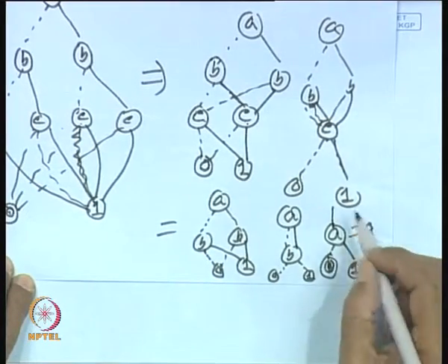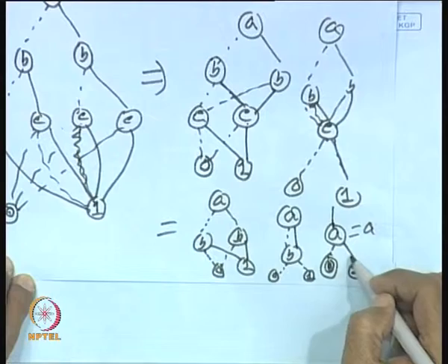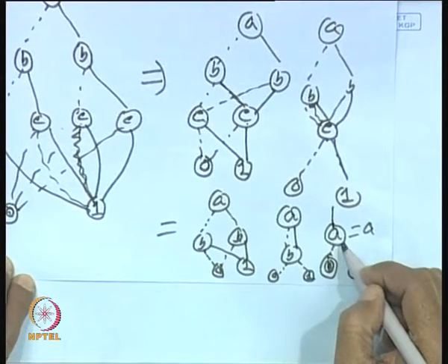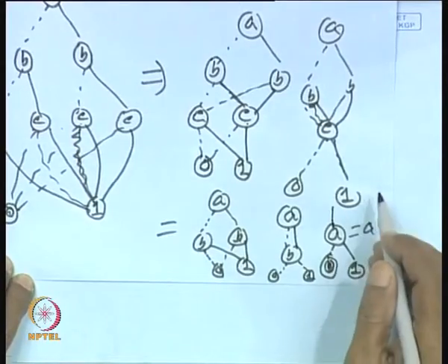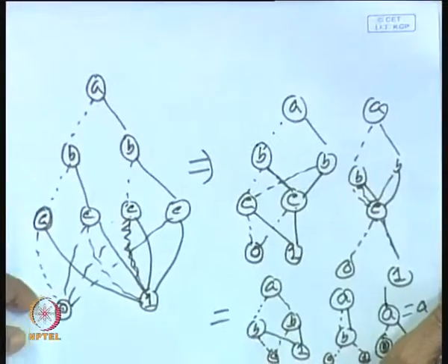So, it is independent of B and C. So, when A is equal to 1 it is going to 1 and when A bar is equal to 1 it is going to 0. So, it will realize a function A. So, this is a very redundant function. We find that all the edges and nodes are getting removed because of this minimization.